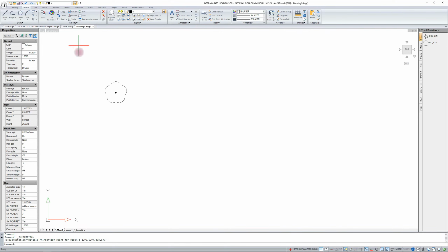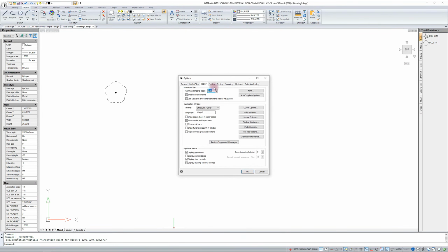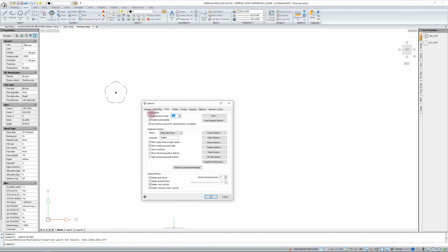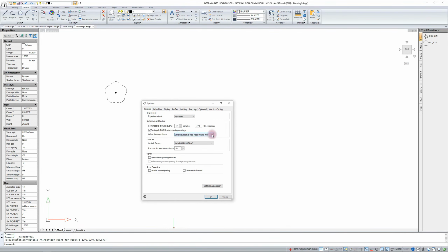In conclusion, I would still like to remind you of a rather important thing, namely the settings in the options window. I already talked in the first presentation about autosave and that this should not be turned off. But I didn't mention that by default, when the program is closed, the autosave files from the app data directory are deleted. Switch it to keep autosave files, or as a last resort, if you do not want to have these documents, move them to the recycle bin.